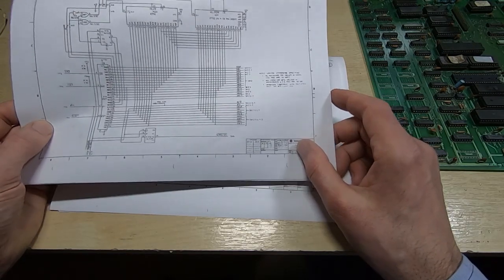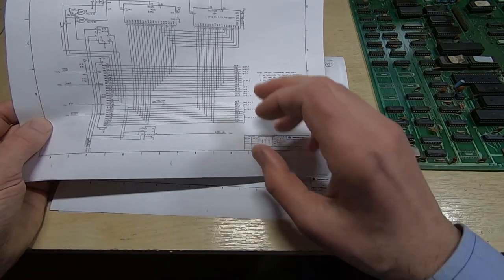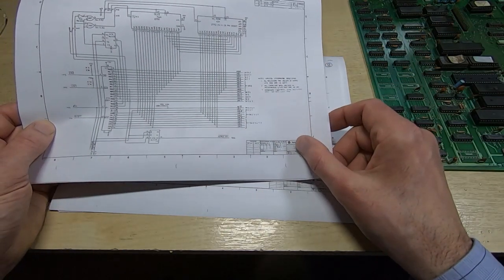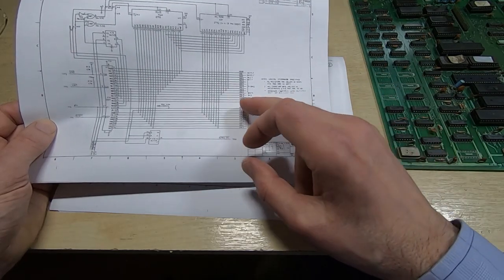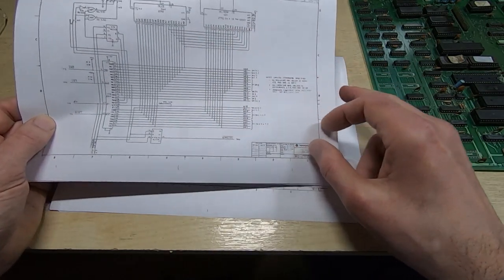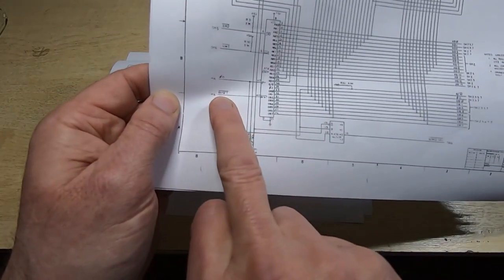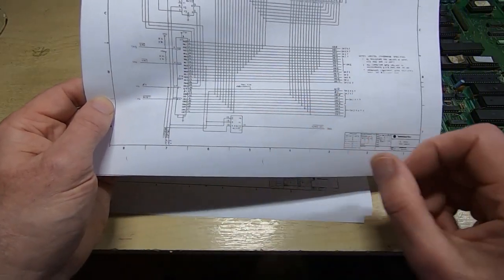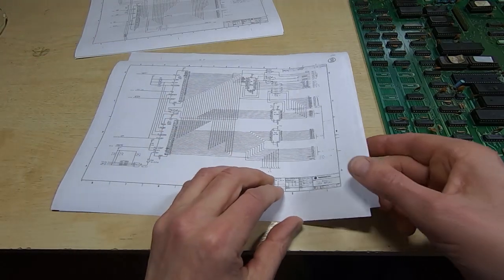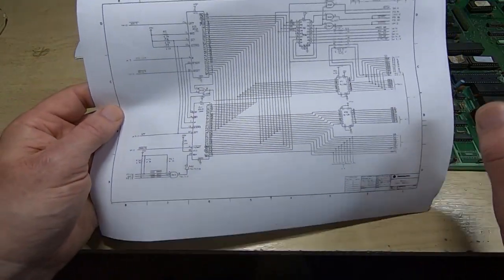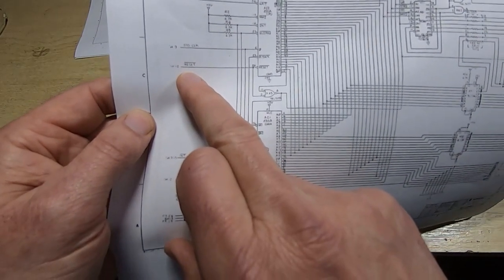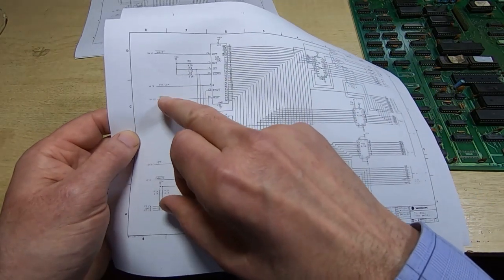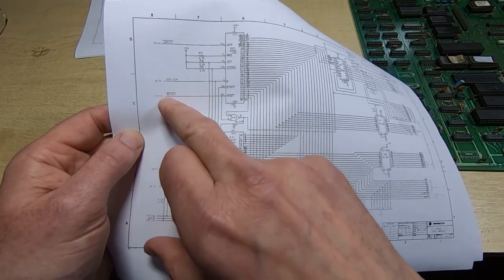For example, the reset signal for the Z80 is controlled from the 6502. So the 6502 can reset the Z80 computer. However, the reset signal throughout is identified as reset. If you can see this, it's reset with a bar across the top, and that's consistent throughout apart from in two places. But that's included in here. So if we look on the Z80, it's also identified as reset, but that's not the same connection. If you try and buzz it out, you'll think the board's faulty. It's got exactly the same name, but it's not the same line.